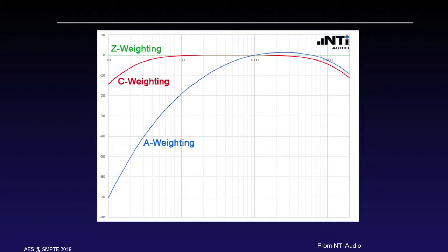And just to give you an idea of what these weightings are, dBA just cuts a lot of the low frequency energy, which in today's soundtracks, there's a lot of it. dBC is almost flat and Z is flat. So when people talk to you about sound levels and they say dBZ, dBA, this, you can understand what they're doing to it. The baseline calibrations, RP 2095 and 2096-1 and -2, talk about this.